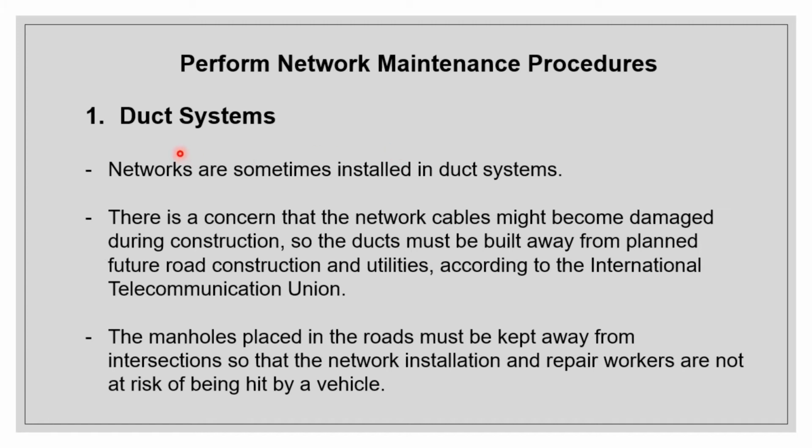First, the duct systems. Networks are sometimes installed in duct systems. There is a concern that the network cables might become damaged during construction, so the ducts must be built away from planned future road construction and utilities according to the International Telecommunication Union. The manholes placed in the roads must be kept away from intersections so that the network installation and repair workers are not at risk of being hit by a vehicle.